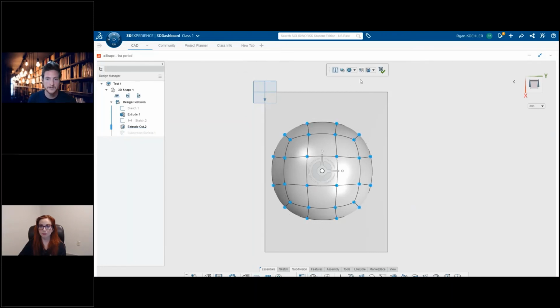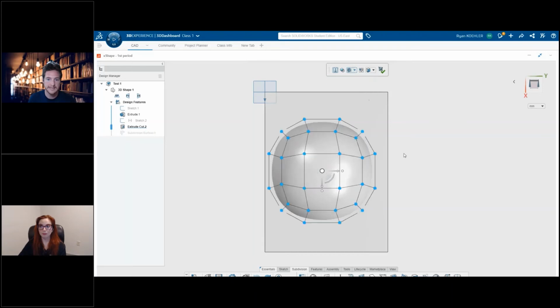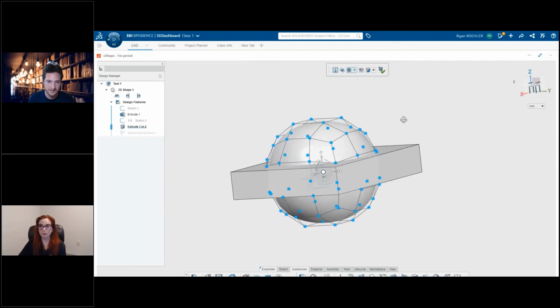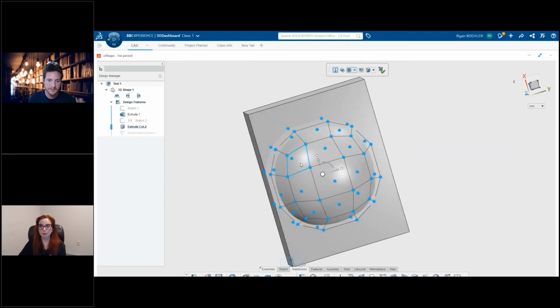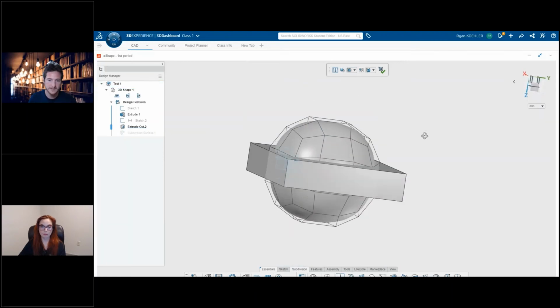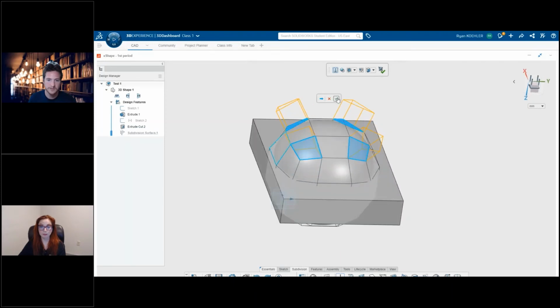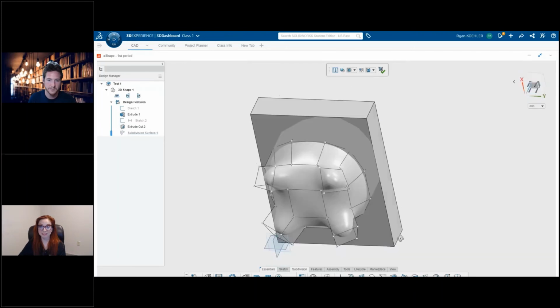So once that's in there, I'm just going to turn this cage on. The cage makes it a little easier to see things. You can see this cage above. And I'm going to go to the bottom side. I'm actually going to hold down Control, and I'm going to select these 4 points. And I'm going to click this extrude button. And what that's going to do is that's actually going to extrude those. It's going to show a little sample. We're going to extrude those out, make little feet for this guy. We got some feet for him now.